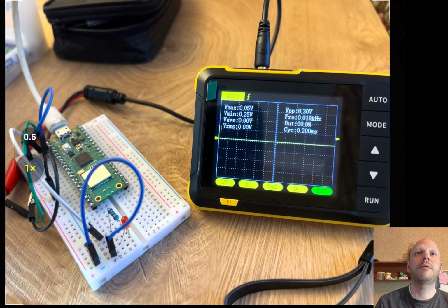It's giving 3 volts every time it's on. Each one of these boxes is 1 volt, and it's up here right at 3 volts, so 1.5 of these boxes. Or excuse me, each one of those boxes is 2 volts. So it's 1.5 of those boxes. That's 3 volts, and you can see it's cycling on and off with that duty cycle. Letting a little water flow, no water. Little water, no water. And that's giving us a reduced brightness with our LED.